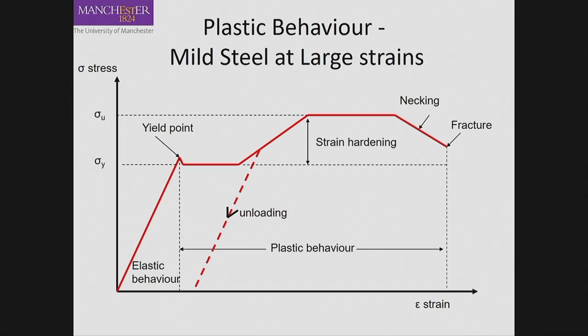So if you are loading the specimen and the stress is increasing and so is strain, let's say you are halfway up there, and now if you take away the force, you will come back along the same path to the original one. It's almost like if you push this foam specimen, and I take out the force, it comes back to the original shape and form.